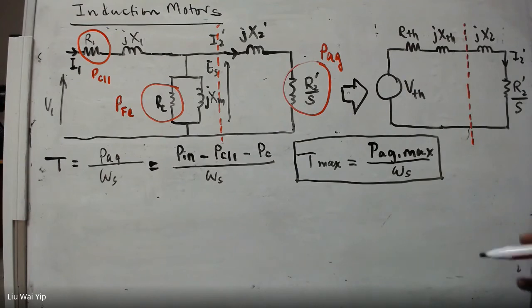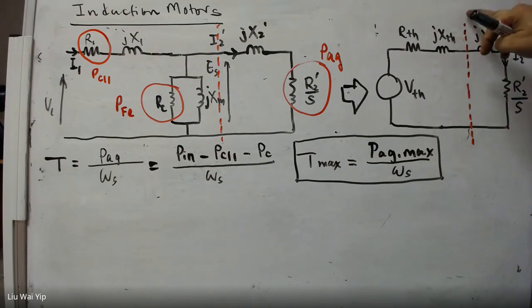And in order to maximize the power, we need to come up with some figure. For the time being, we are not able to modify the reactance of the rotor, but instead we can change the slip in a way to change the referred resistance of the rotor. So let's do it.